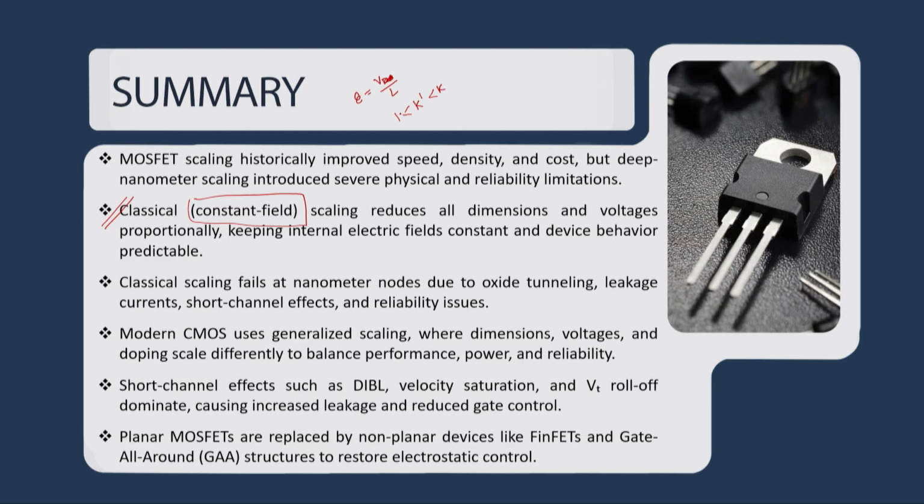Then post 2011, when the FinFET was introduced, we entered from planar MOSFET to non-planar technology, and hence we were moving in reduction of the dimensions from 22 nanometer or 32 nanometer to 1 angstrom, right. That is what comes under modern scaling. Modern scaling is not following a prescribed rule, but yes, we are maintaining the integrity of the planar MOSFET. The physics and the mathematical modeling of planar MOSFET, what we have discussed so far, is simply applicable in non-planar devices with proper optimization and modulations.